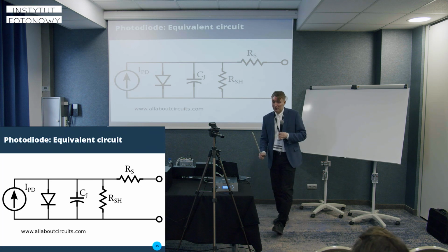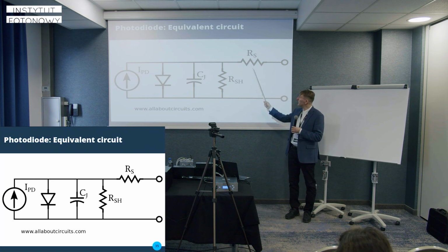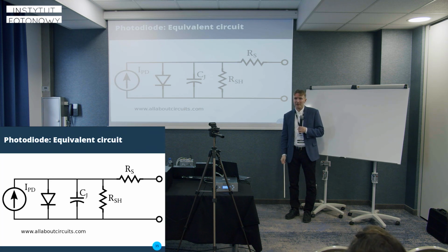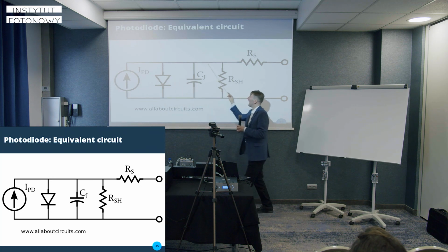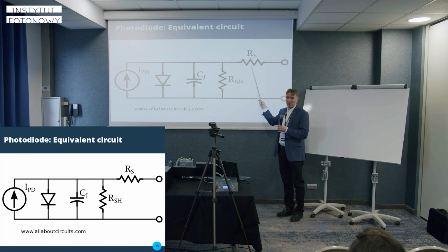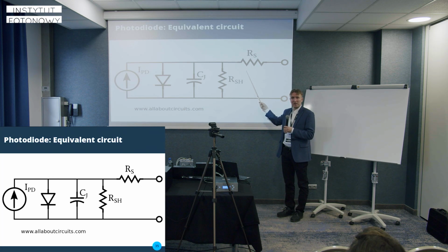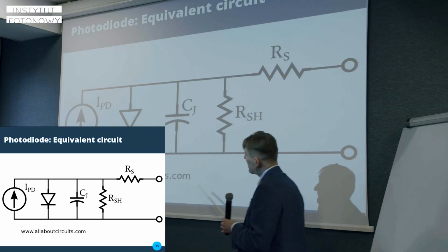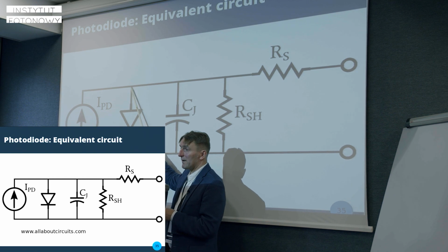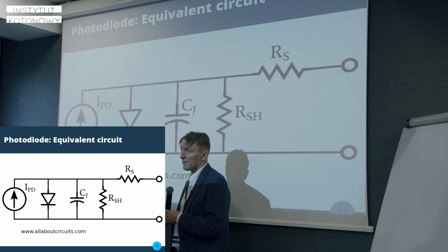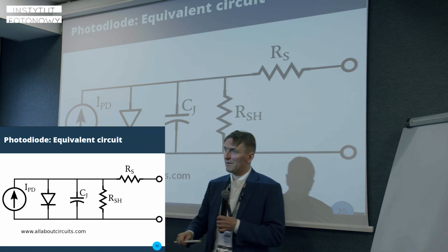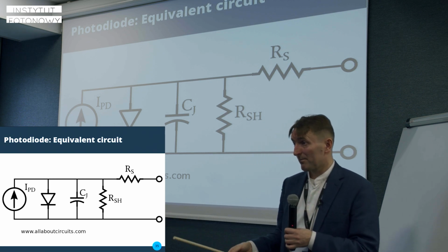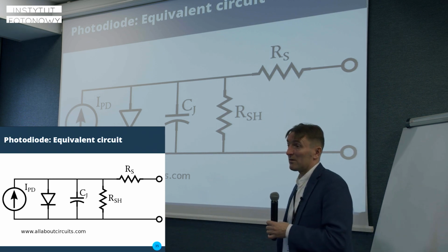So it is all good when this serial resistance is low. If it is high, there will be current flowing here, and there will be some voltage drop on that resistance, proportional to the current and proportional to that resistance. The plus will be here. That means this plus also will be here, and the current will go through that diode. And the diode is nonlinear. So our detector loses its linearity, because you have this resistor here.